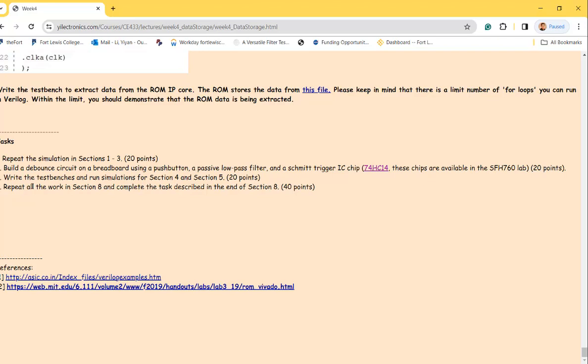So to know this one will be very beneficial for the soft core experiments, maybe in 3 weeks from now. Think about that. When you guys are putting a soft core into the FPGA, it's a very simple basic storyboard. You're actually putting a CPU in it. And combining with the memory over there, you can put all your assembly code in the ROM, the read-only memory. So you're creating a little microcontroller similar to whatever you guys are learning this term in the microcontroller class. So you're creating an Arduino, not using an Arduino.